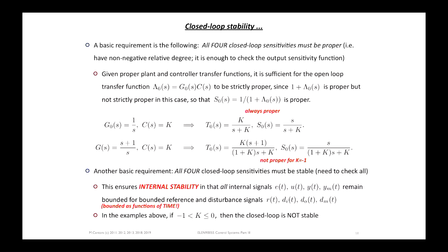You can see here that in this case, and we're not looking at all four, you get transfer functions in closed loop that depend on the parameter k. We've seen that sort of thing before, and like in problem set 2, you can just look at the poles of these to determine whether or not the closed loop is stable.